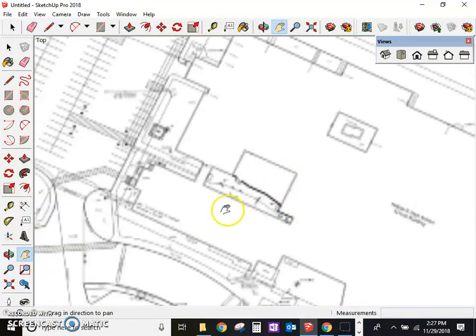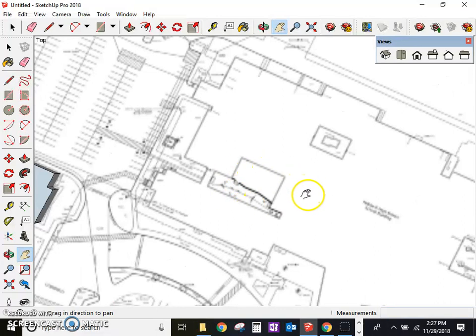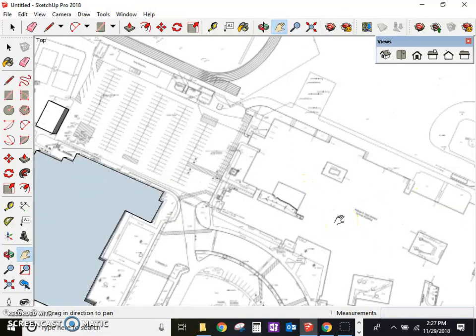So we're gonna have some work going on in this courtyard. One thing you may want to do is, if you draw the geometry of the courtyards before the exterior of the building, they could be a separate geometry, so when you extrude it, it doesn't fill those in accidentally on you. But we're going to have a lot going on in the site.